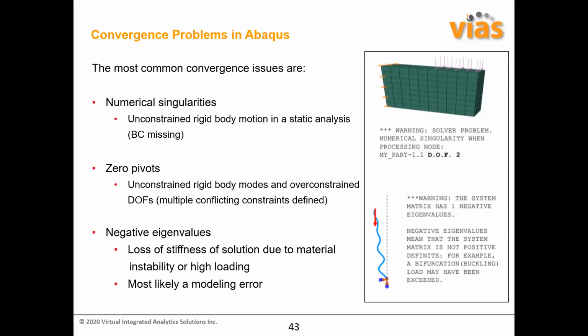So for example, in certain regions where you needed to define the boundary condition, you define the boundary condition, but then you define certain other conflicting boundary condition, or you made it like a slave node or slave surface or the master surface at another point, then that may also lead to the unconstrained region. So Abaqus may not know exactly what the boundary condition is. Then it tends to ignore every constraint on the body. Then you are left with the zero pivots.